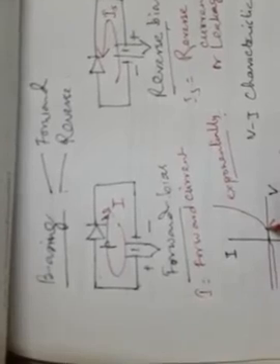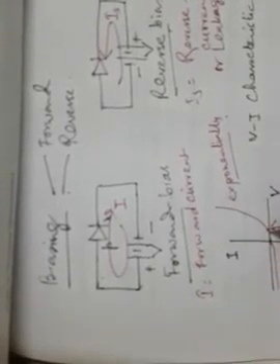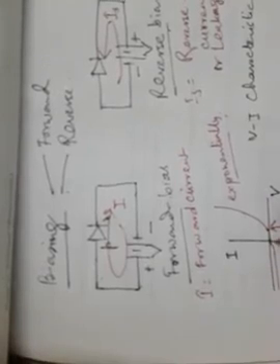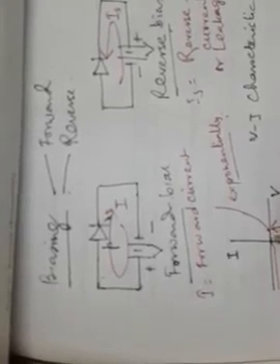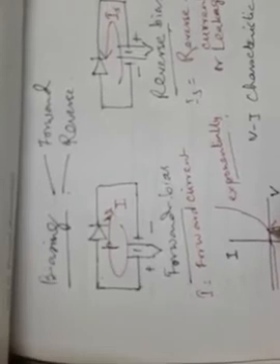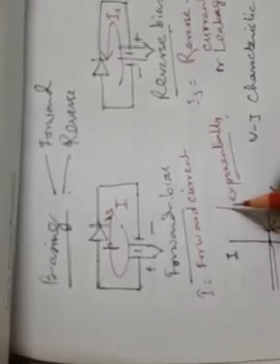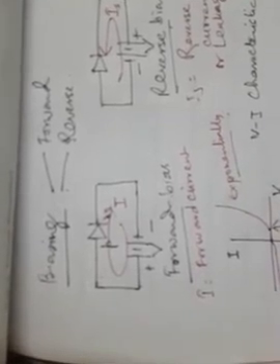which is treated as the boundary of a forward biased diode, below which the diode conducts very little. That means it is almost in the non-conducting state. Absolutely negligible current will flow through it, ideally zero, but after crossing over and above this cut-in voltage or knee voltage, the diode conducts heavily and the current will rise exponentially.